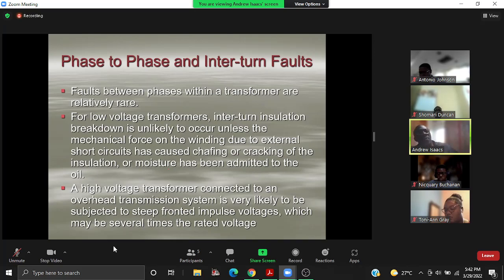Yes? And we looked at the fact that depending on the connection at the load point, when you energize a line, you at some point may have a doubling of the voltage. Remember when we did that? With all the reflection and refraction and all those things?